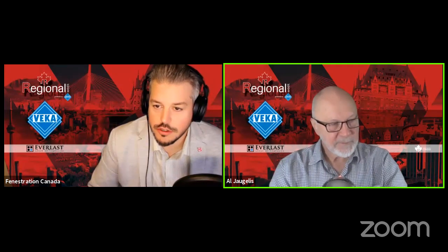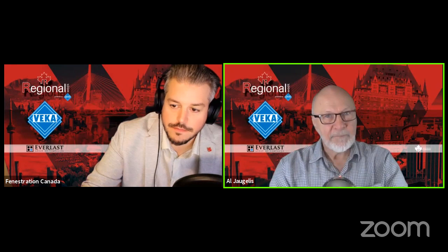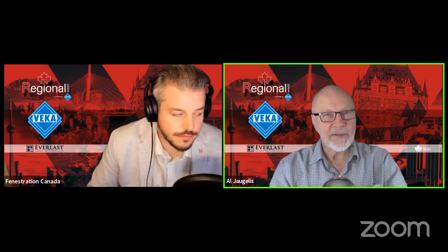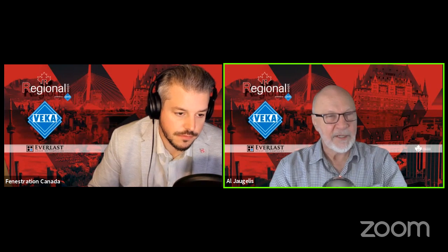Well, about that, someone just wrote, yes, it is done that way. Many vendors ship their large patio doors in knockdown condition to site here in Canada, where the sashes, frames, and sails are then assembled at site, including fold-in doors. That's okay. Folding doors do. Yeah. But here's the thing. Folding doors are now in the scope of NAFS, and they're expected to perform at the job site. And Part 9 of the code doesn't have any site-built door exemption in it that I know of.